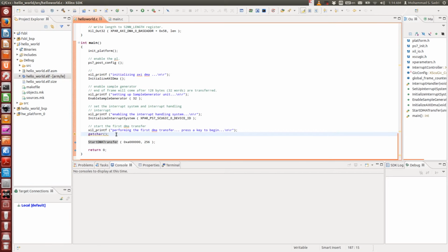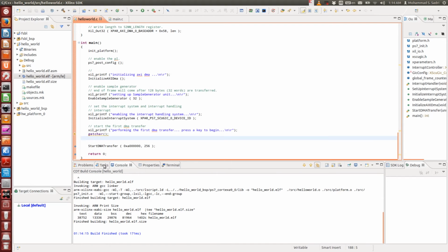So for example, let's make a silly change in this code and look at what is happening in the console when I save this program. I have changed something, so automatically your code gets compiled. And how does it get compiled? Using this compiler, which is actually a cross compiler running on your x86 platform and compiling your code for your ARM platform. And I use one utility provided with this toolchain to disassemble the ELF which is generated.